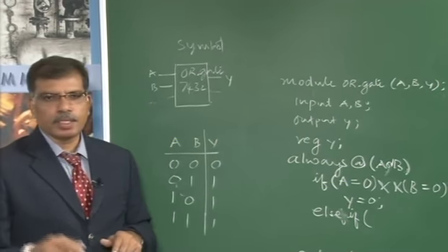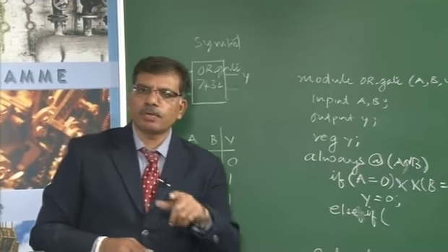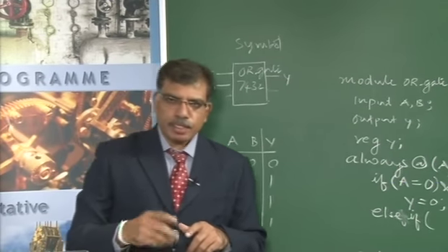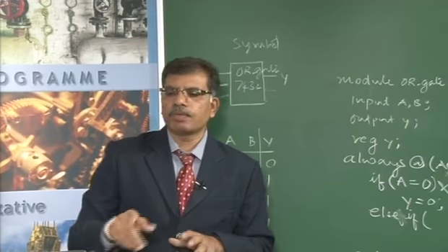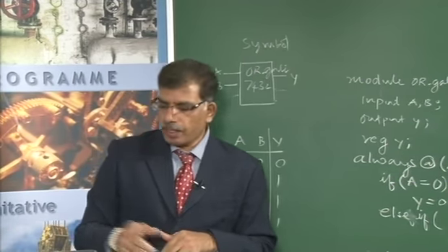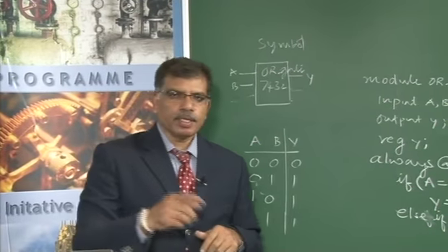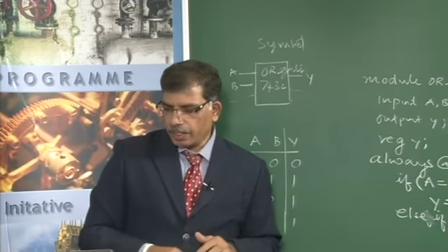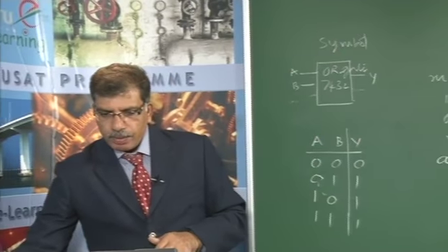you can write the test bench and that test bench can be linked to your model. Automatically that test bench will generate the input waveforms that will be given to the model that you have written, and you can see the output from the ports that you have defined in the model. So next we will see how to write a test bench.